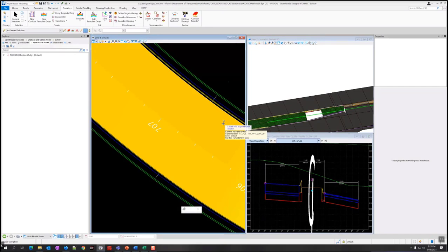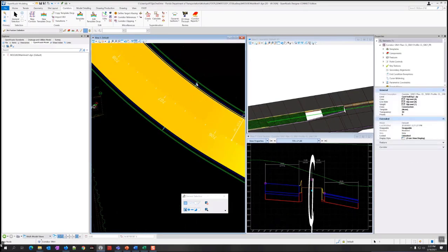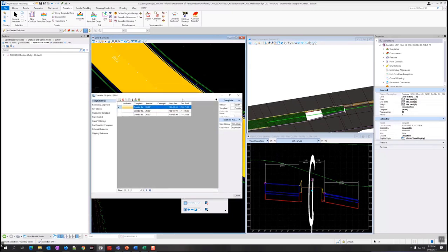So that's the next exercise, 3.18. We're going to look at the super elevation point controls. So super elevation essentially creates a point control. So if I go here to my corridor objects, I can do it there, or I could just grab this corridor handle and I can do it from there. So I've got it right here. Should be in one of these here. Yeah, corridor creation tools, a little hammer. And the bucket is the first one in the list, the corridor objects.